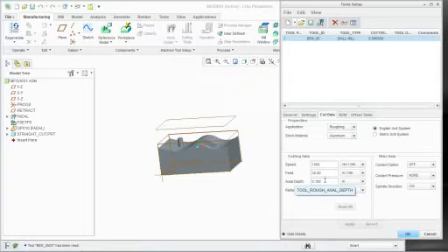Now, if I have multiple materials that I am using, I can fill this information out against multiple materials. And whatever the material is that I have selected in my operation, it will automatically adjust to whatever I have saved for that. Okay, so if you fill this out one time, if you go back in again and start something fresh and brand new, when you start your operation and you say I'm going to have aluminum, when you go in to pick your tool, you will automatically have this information filled out.